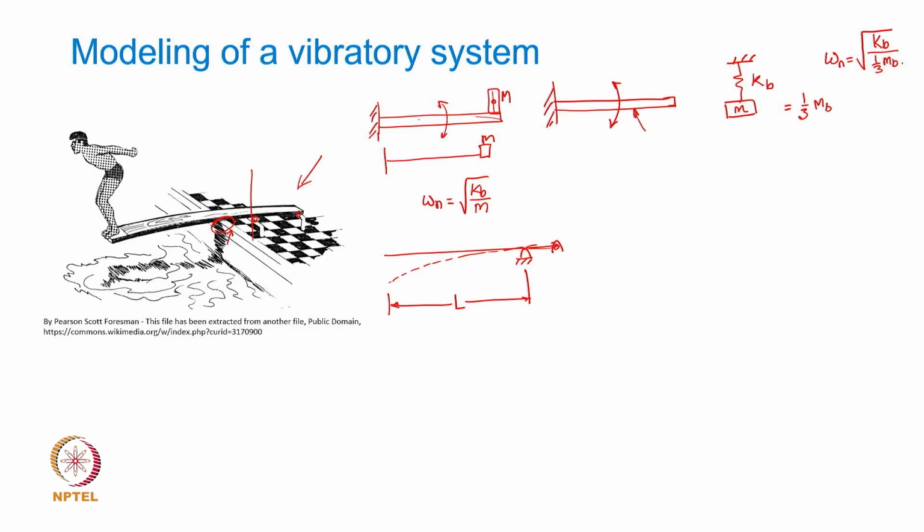When it swings up beyond this equilibrium position, the deflection will be fulcrumed around this, because if it goes up and loses contact with this particular support, which appears to be the case here, then it is going to have a different effective length in the upper half of its rotation or vibration than it has here.